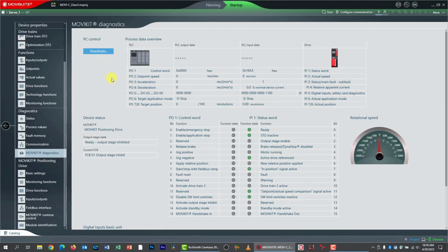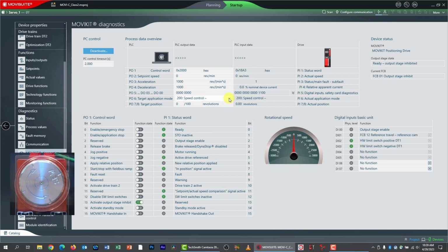Take control of the axis. I'm going to change my mode to reference travel offset via field bus. I'm going to just leave my offset at 0 here, and I'm going to trip referencing again. Of course, I've got to enable my drive first, so I need to turn my hardware controller inhibit on, remove my software controller inhibit, enable my drive, and I'm going to start referencing.